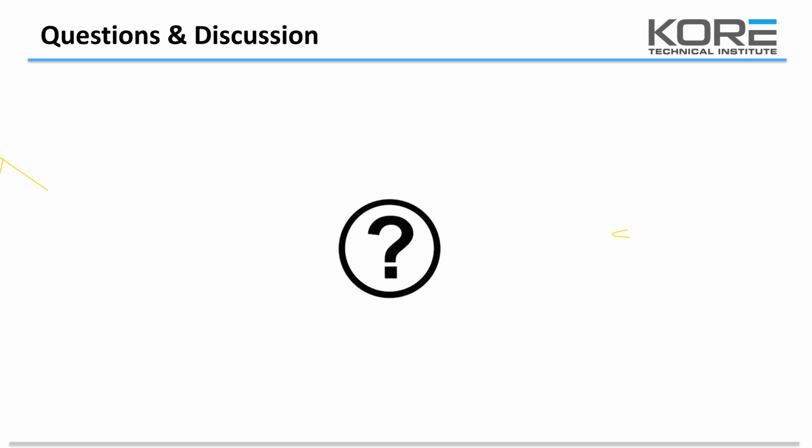So when you get it down to where it's not moving much gas, what little of the scroll is compressing is basically not moving any gas through it. It is doing some compression for part of its scroll cycle, but when there's not enough for it to take the next gulp over and keep that going, it's just basically bouncing on itself. So you're doing partial compression, but it's not moving through the scroll.